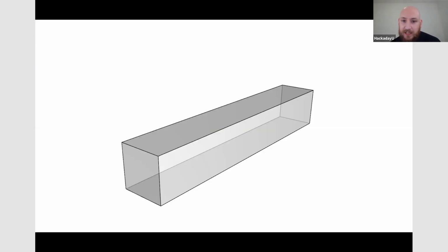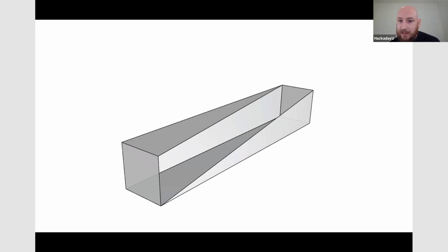So this is an example that you probably know already, which I'm just going to go through. We could draw a box in 3D, explode it and delete two surfaces from the polysurface, create a triangle on the top and a triangle on the side, and then do a sweep to surface using these two edges as rails, and these two edges as the cross sections. That, drawn in Rhino, would not be adjustable in any way. We could scale it, but that is a permanent change.